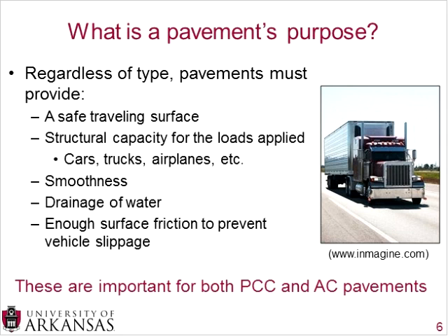You also want to make sure that the pavement is smooth and is able to drain water. Water pooling is a very significant problem that can cause hydroplaning and increase accidents. And finally, you want enough surface friction to prevent vehicle slippage.